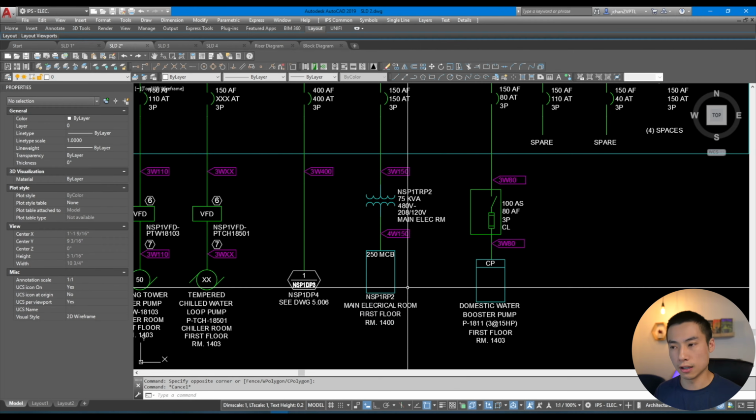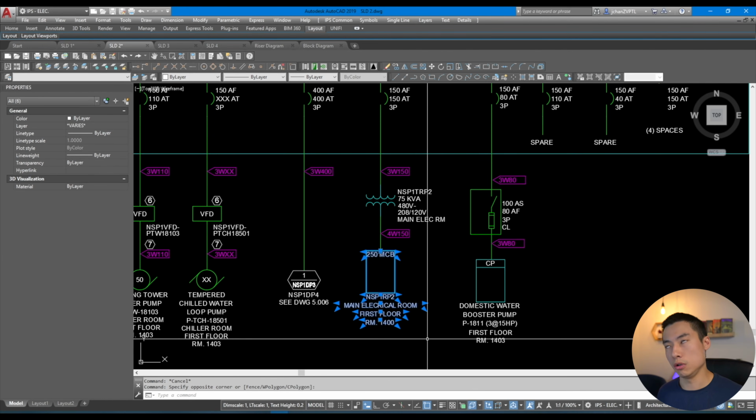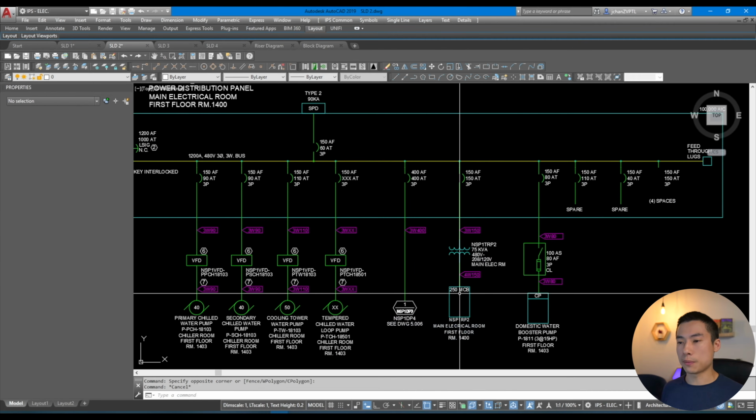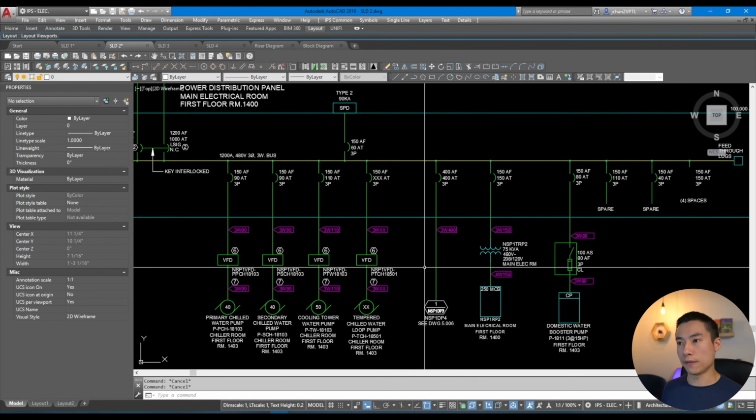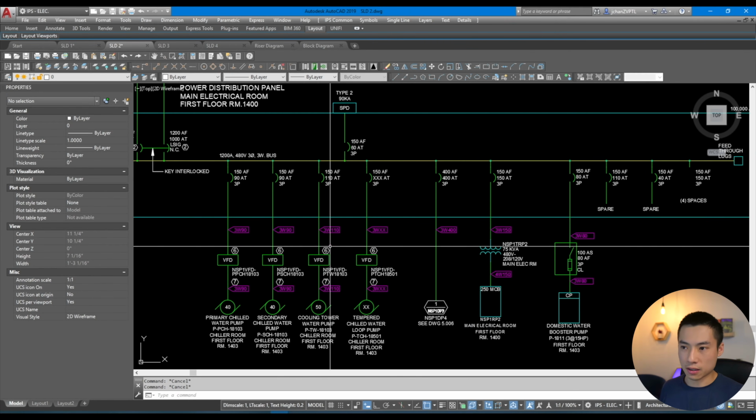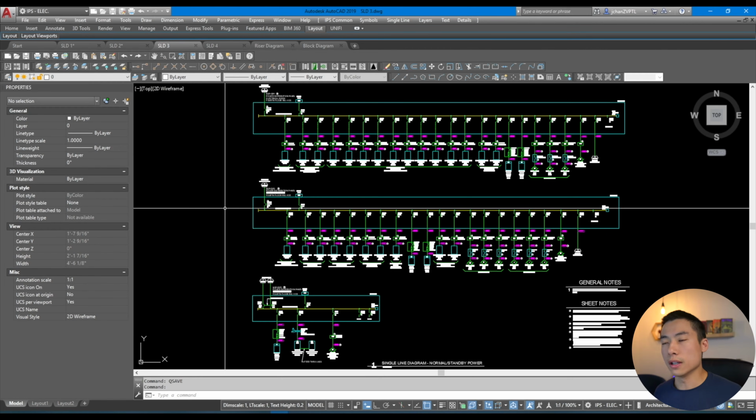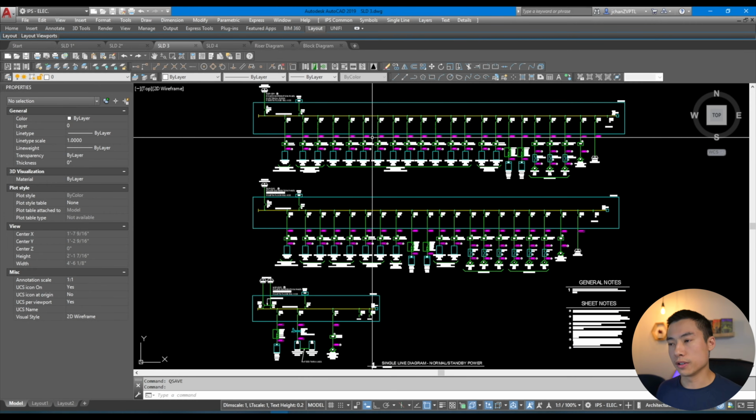So everything after that is just single pole to a receptacle or to a light switch or something. So like from here on down, you could just show a panel schedule. You don't have to show a single line diagram for everything. So the diagram usually stops at a point where it's simple enough that we don't need to specify all of this stuff here.